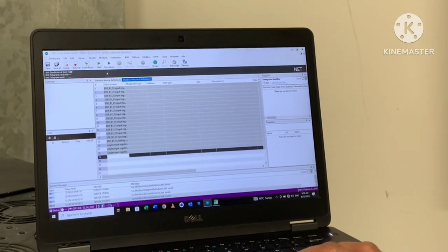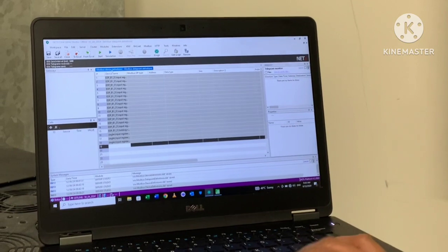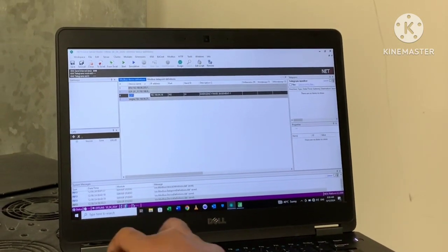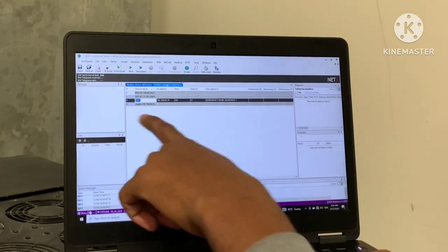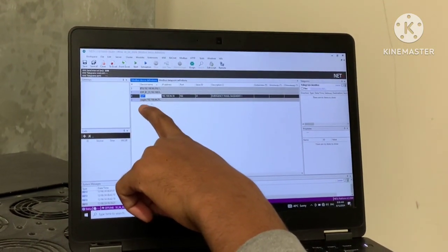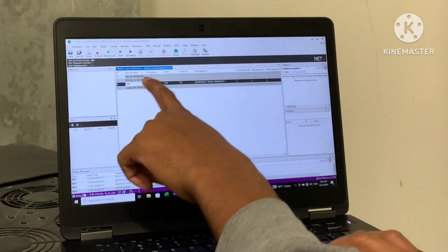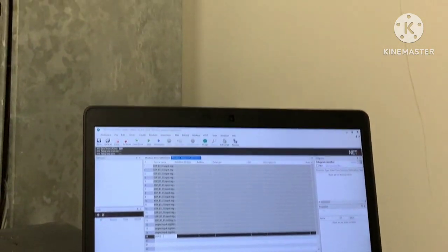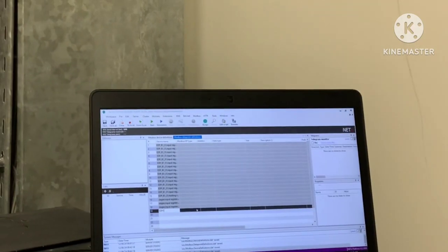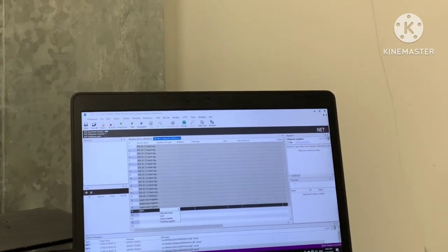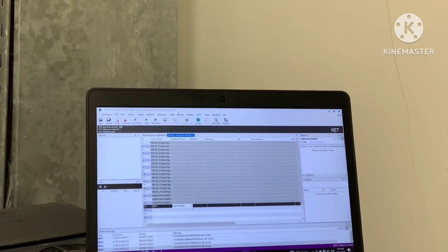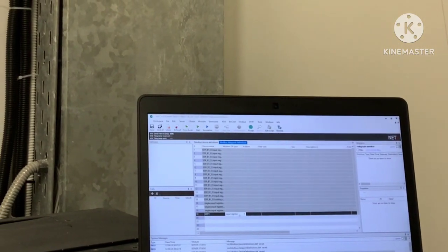It's asking first for the device name. The device name you added before must be the same. If not, you will not get any value from there. So the first device name we put as EDP1, so on the data points itself, I will make the device name EDP1. Okay. And the Modbus data type. What is the type of the data? The data type is holding register or input register. You can read any value. Okay. So I'll select the input register.